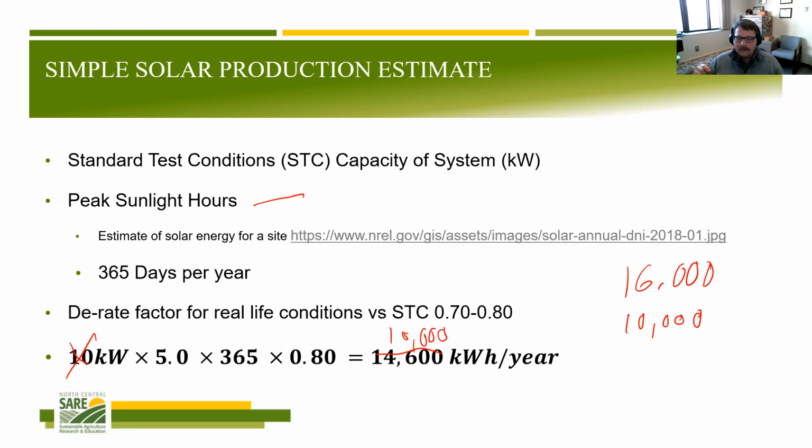And so one of the calculations that your installer is going to do is figure out what is the absolute maximum voltage when you have the minimum temperature. So they're going to look at that polar vortex and say, well, I can hit negative 30 C. If I can hit negative 30 C, what's my maximum voltage and power? And I've got to match my inverter based on those numbers at the lowest possible temperature.